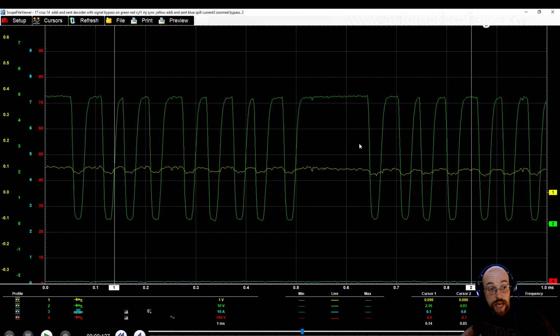This is actually a 24-bit binary signal. It's two 12-bit channels that are averaged, and the final averaged output goes out as an analog signal that can be used for dynamic fuel system testing. And this binary number that it puts out is equivalent to what your PCM would be getting and you'd be able to see on your scan tool.